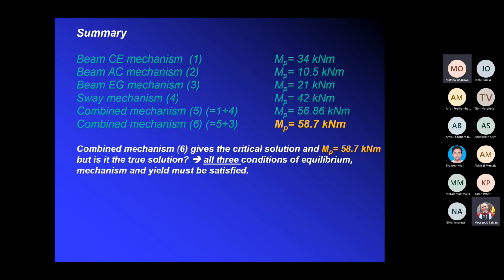But for the moment, remember this is the plastic moment, and therefore when you are looking at the structure, the highest moment is the one that causes the total collapse. For the loading, you are looking at the first load that will give you collapse. That's your critical load. So remember this, please.